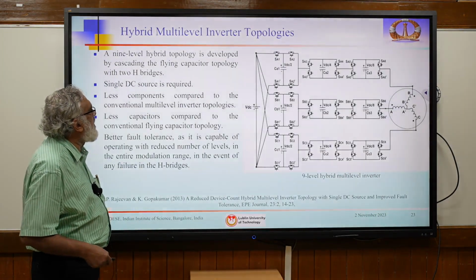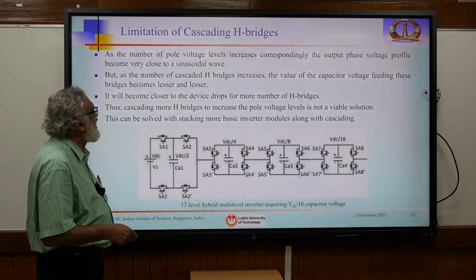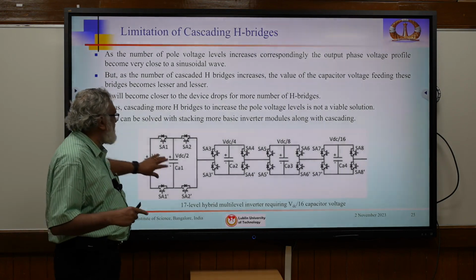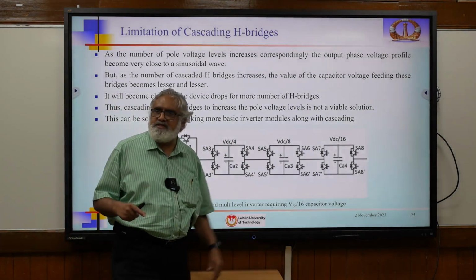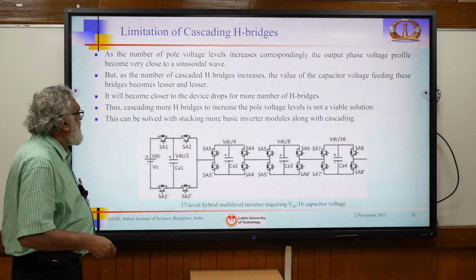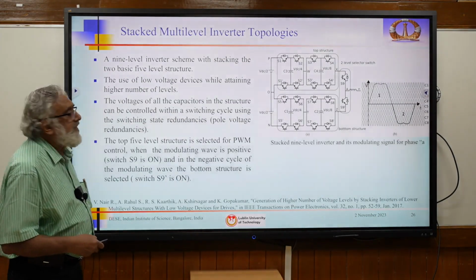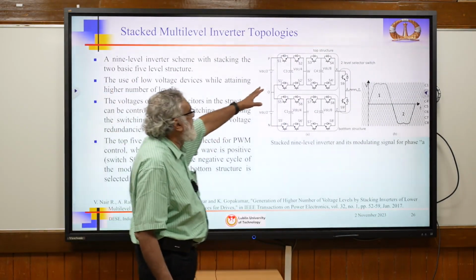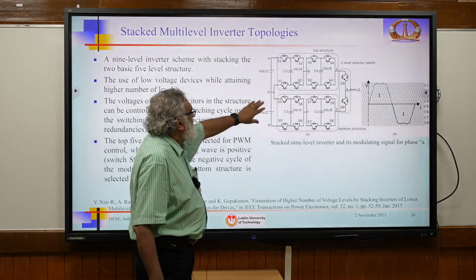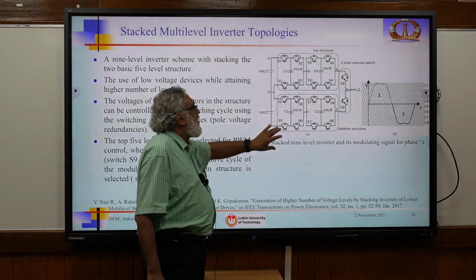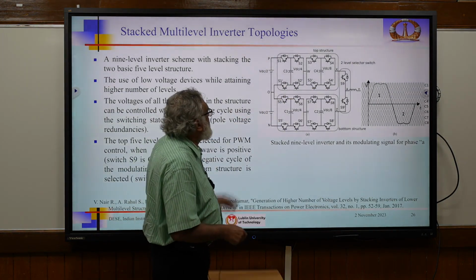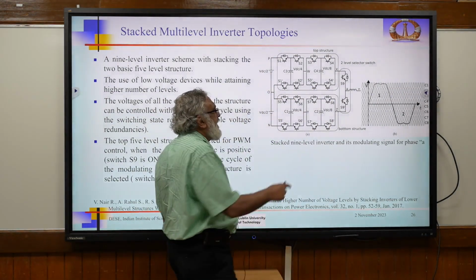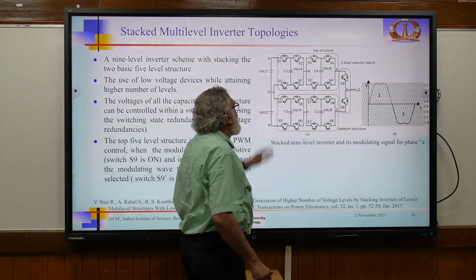Then we came, if you see the A phase, you have VDC, a flying capacitor and 3 cascaded H bridges. So this can be modified. Then can we have, instead of 17, 9 levels? 9 levels are also possible like this. Here we found these are symmetric, here, here and here. If you see the PWM level, 9 levels means 8 level-shifted triangles are there. In this region 1, the upper region, only this is working.